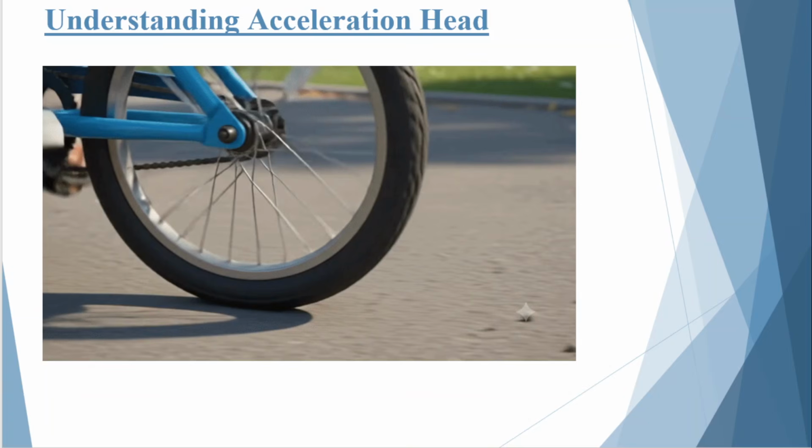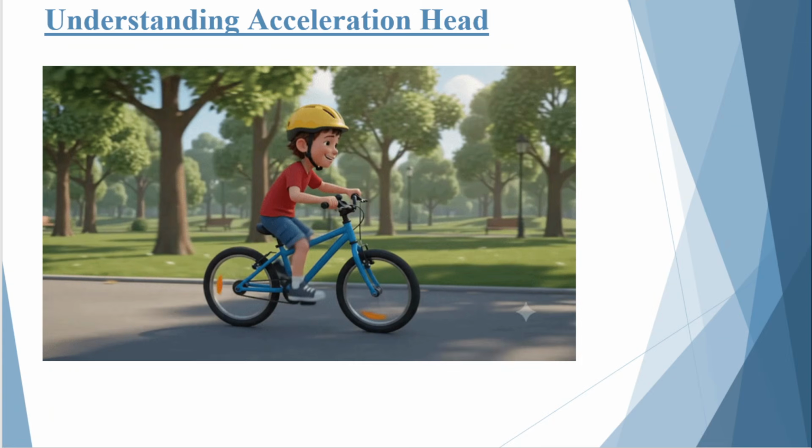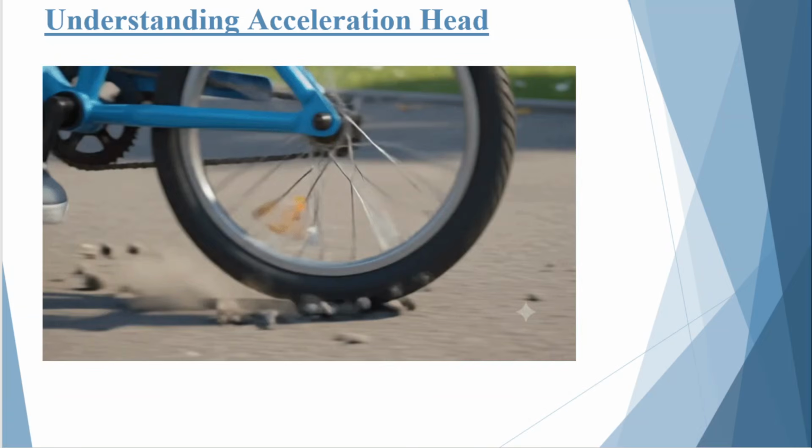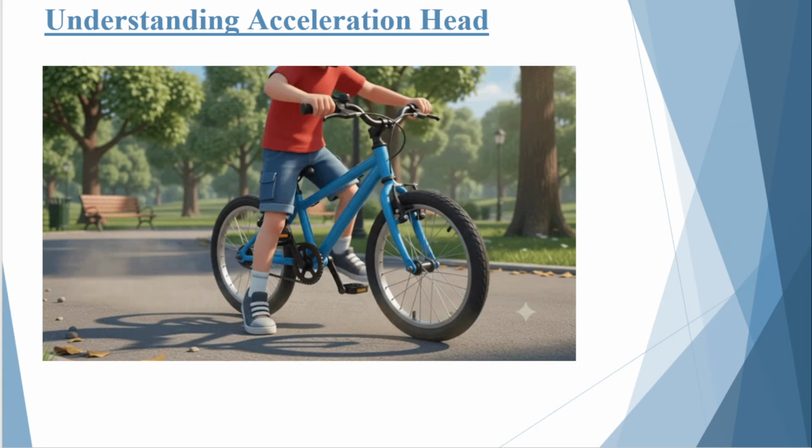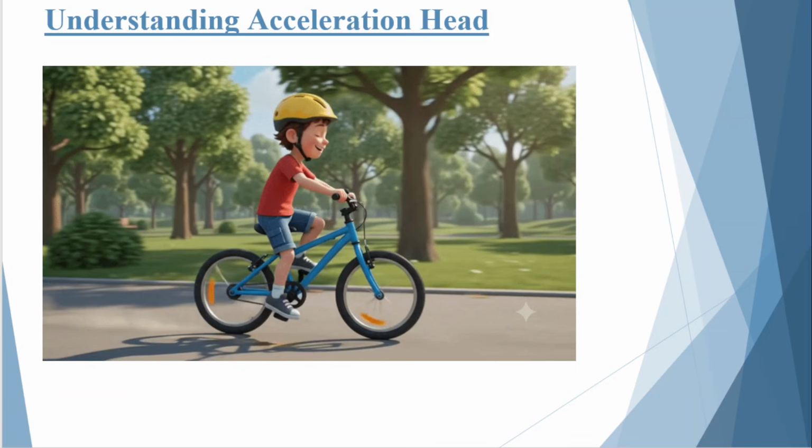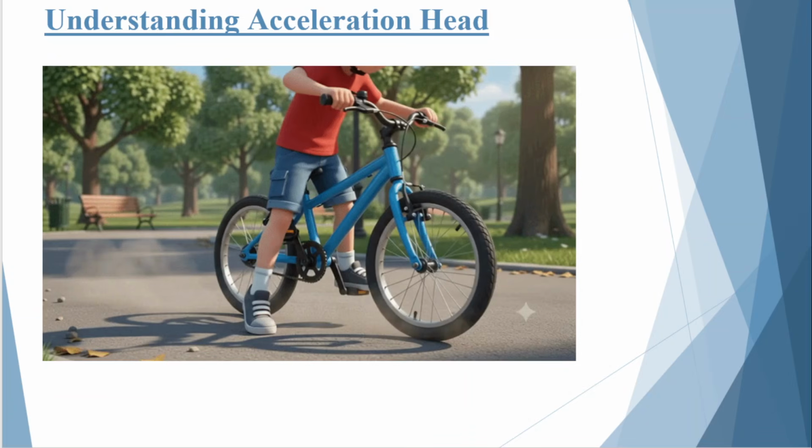Another important observation is the effect of pump speed. As the pump RPM increases, the piston accelerates and decelerates more rapidly. This means the liquid requires even more energy to change its velocity, resulting in a higher acceleration head. This is why high-speed reciprocating pumps require careful hydraulic design.